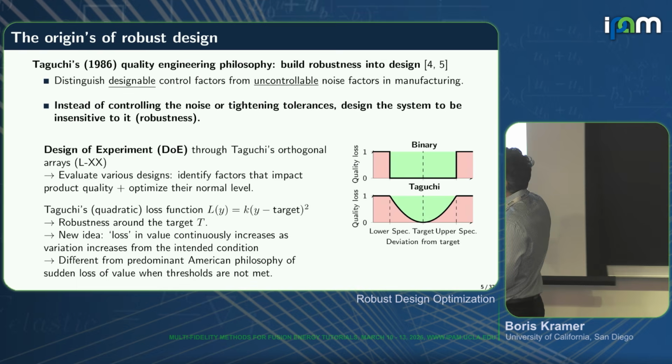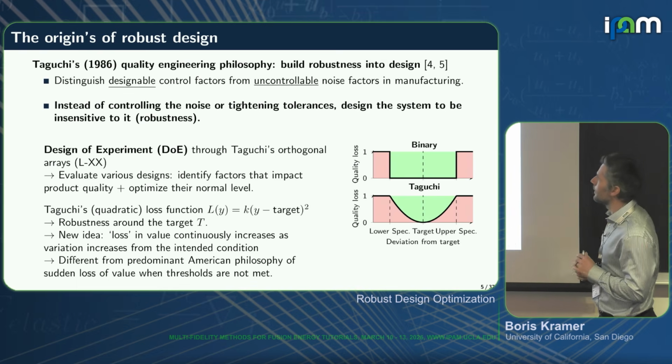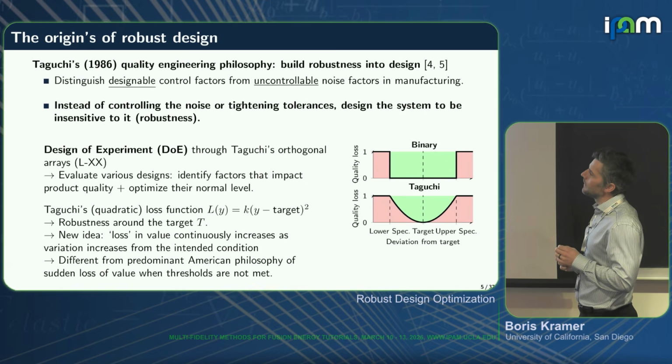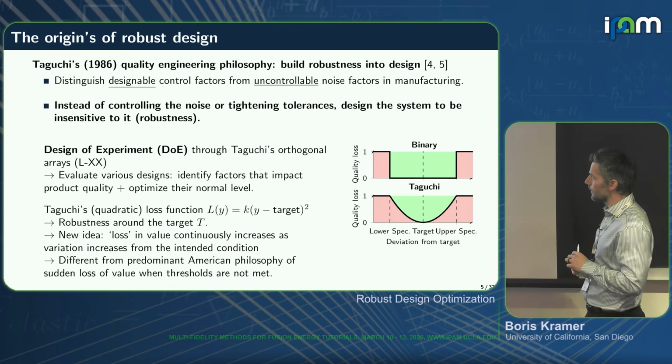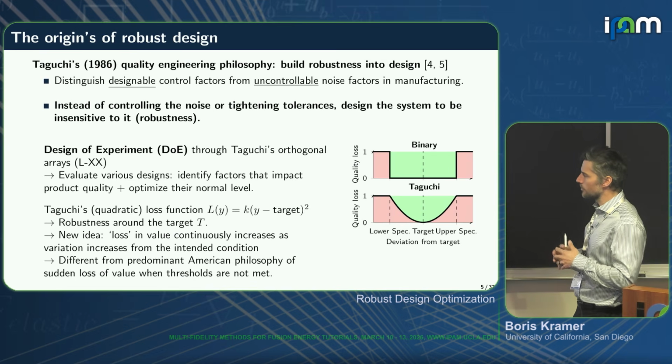And so instead of controlling noises and saying, well, this system can only take this much or that much, or tightening tolerances, the idea of Taguchi was to make the system robust. So it's actually insensitive to some extent to these noises and external disturbances.